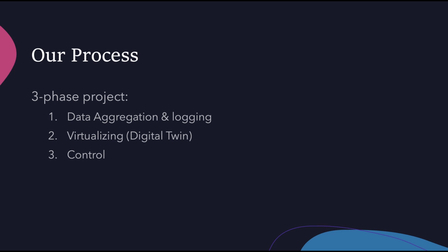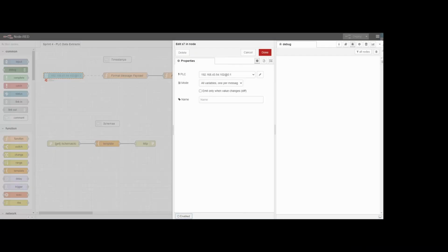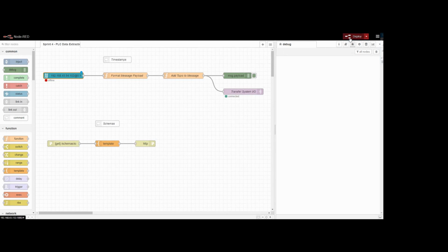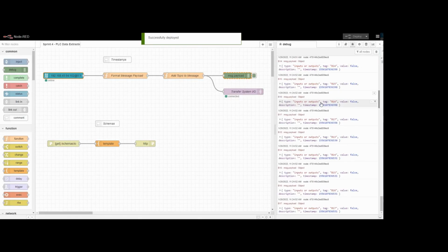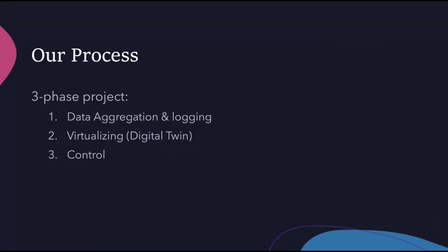So there was something up with the PLC or some configuration on the PLC that we couldn't really figure out through the documentation of the library, which ultimately led us to take a look into Node-RED, which had libraries exactly for the Siemens PLC through a library called S7contrib, which allowed us to actually create a flow-based program, which was pretty high level and self-documenting because it describes a flow of data, which actually turned out to be the most clean solution for our project and also gave the quickest results in the shortest period of time.